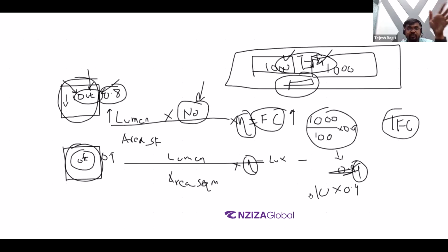Now if we are talking about the average foot candle for this entire room, and it is determined that we require all of the 3 light fixtures, then on a given floor plan you'll have 3 light fixtures shown, and 2 out of those 3 will be on emergency mode. What that means is, in case there is a power failure, there will be a battery backup installed in it or somewhere else, powering the light fixtures, at least till the time the diesel generator set kicks on, and then the DG set will take care of turning on the third light fixture as well.